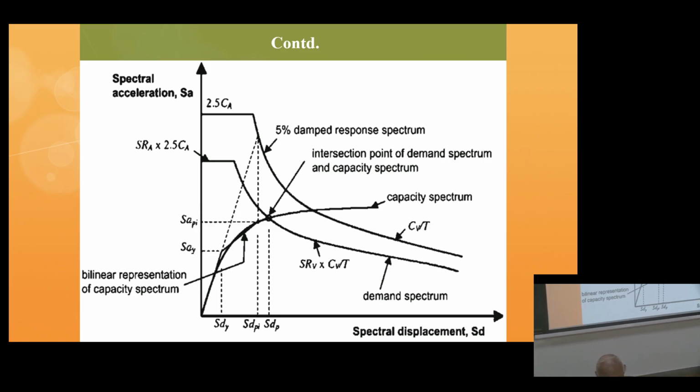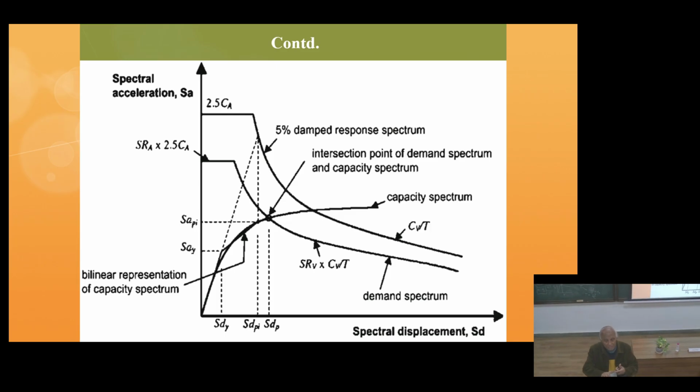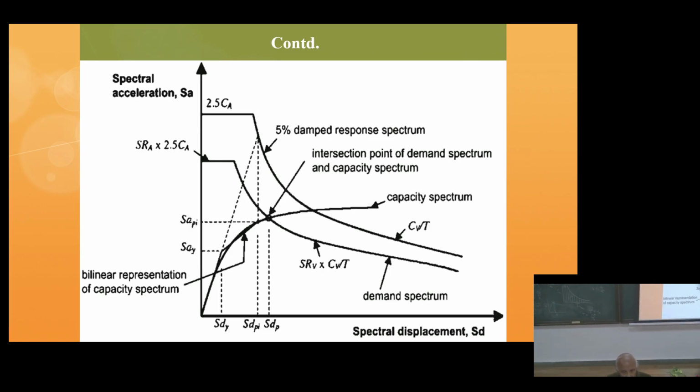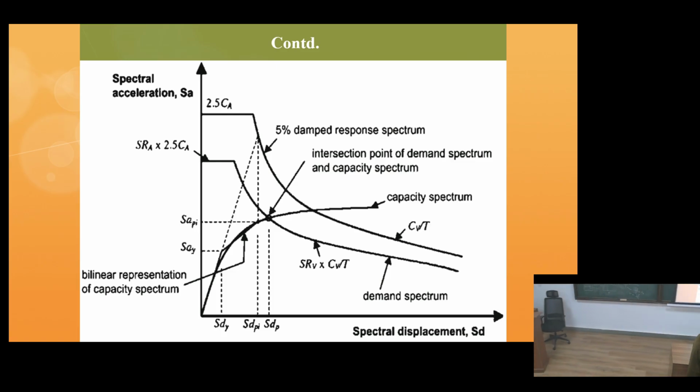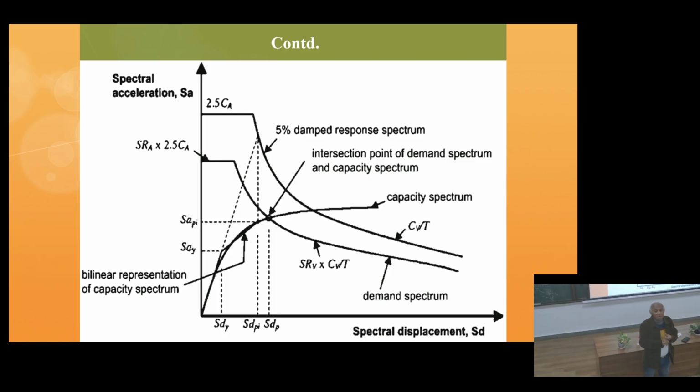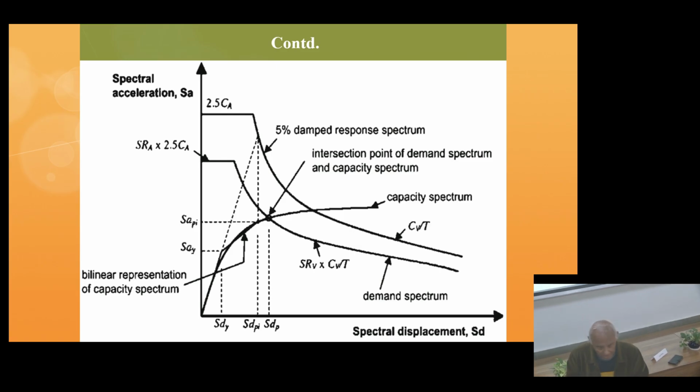So life safety is ensured. That kind of thing is done in performance-based design. So the key is that you are using the CSM technique to define the performance point, and for the performance point, see that if the inelastic state has been reached, then what is the state of that inelastic state, whether it is in the LS state, IO state or CP state.